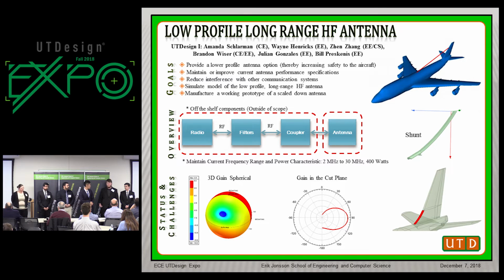That is because the hand radio that we're going to be using only receives high frequencies. So the filter that I designed focuses on 142 megahertz. It is a five-stage pi-type filter. It has about a 600 kilohertz 3 dB bandwidth. And I'll be validating the results we get from ANSYS.